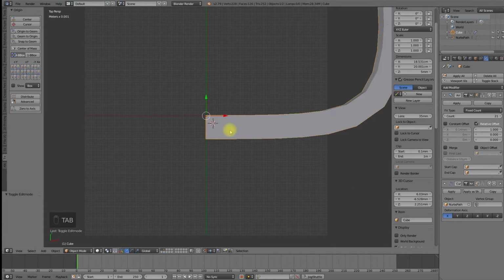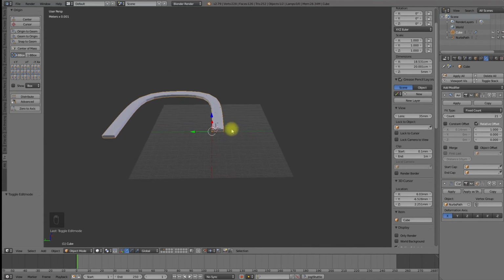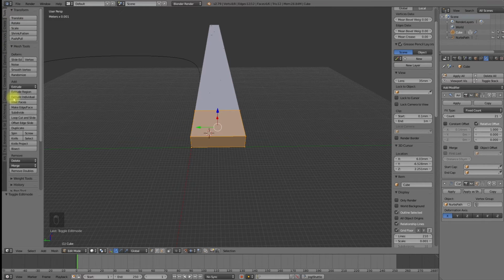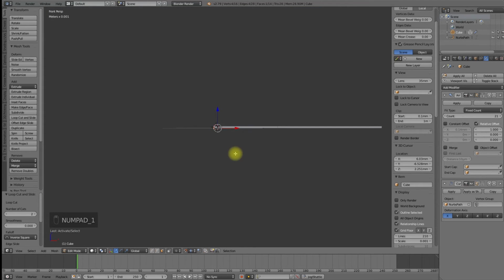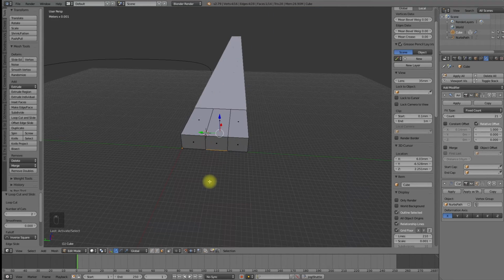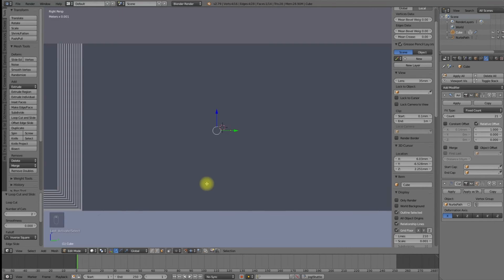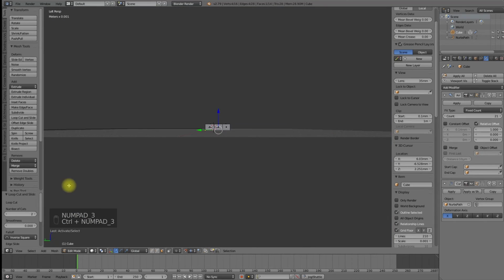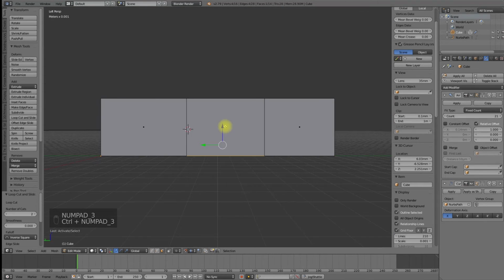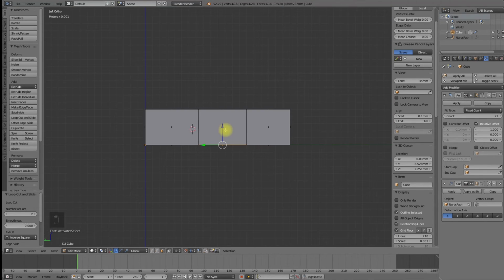Also, if you want to print the outcome on a 3D printer, you can ease the job for the slicing software and prevent slicing errors when you do not have inner geometry, like faces or edges. Afterwards, I set the curve modifier to the shape object. All instances of the shape object will now follow the path of the curve.